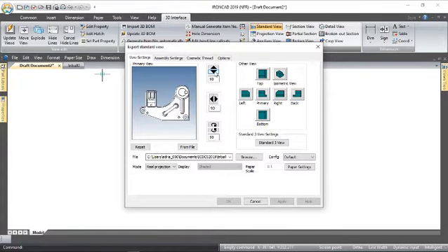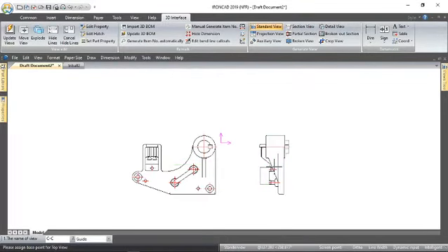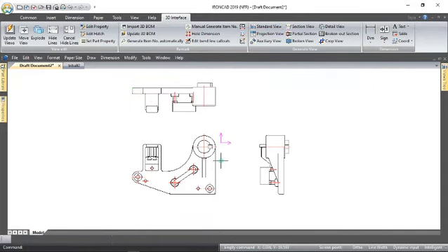These arrows will give me a plan view of that part, and I'll say I want that view as a primary view, I want a right hand view, and I want a top view there, and I'll just say OK. Basically that will go away, and it will automatically create those 3 views like so.